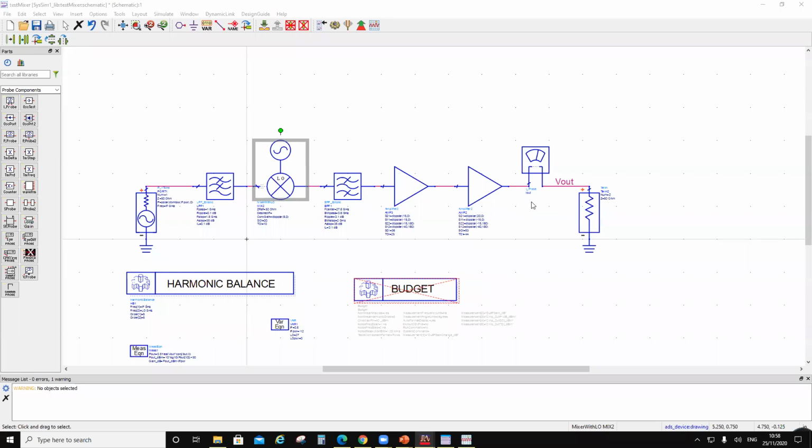For a link, most important is how much output power you're going to put, and how much should be the linear power actually. Now, how much linear output power you should put, that's the question. If we were to start with a back off, I showed you that for a given bit error rate, you might have to back off. So you are designing at a certain linear power, and in that way you have to do the budgeting.